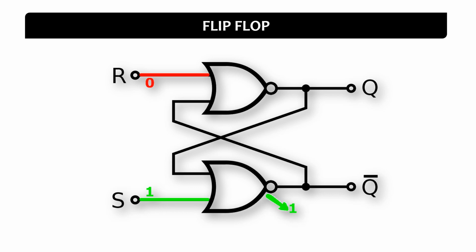Okay, so now see on the screen, we have an animated image of a flip-flop, that is the circuit. As you can see in the image, we have taken two NOR gates. Then we have two different inputs, one is S and the second is R, which stand for the set and the reset process. And we have two outputs, one is Q and the other is Q bar. Here Q is my main output and Q bar is the complemented output, or inverted output, I can say.